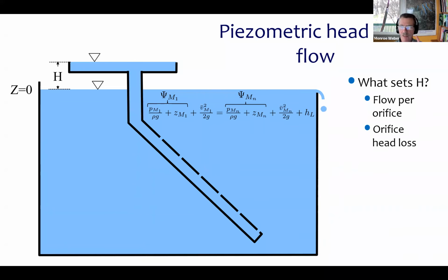And it turns out, unfortunately, that there is, because look, if we put a control surface at 1 and a control surface at n, the velocity in the manifold pipe is different at those two control surfaces. Up here at 1, there's a lot more water flowing through control surface 1 than there is through control surface n. That means V1 is a whole lot higher.